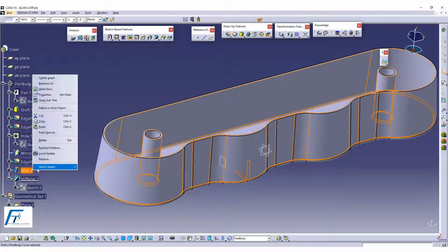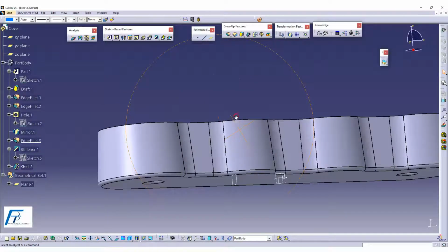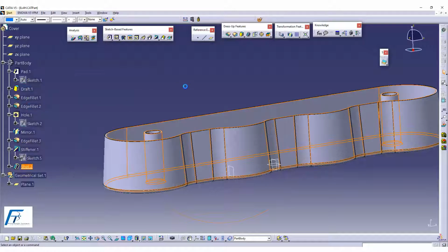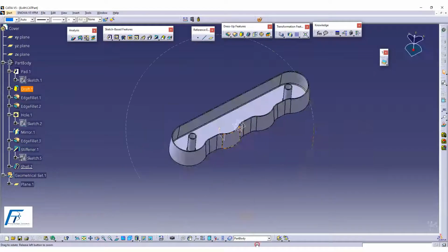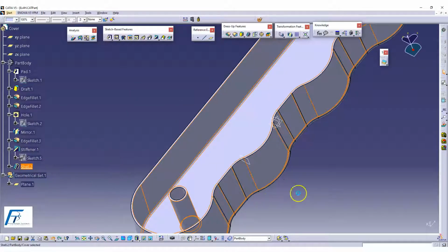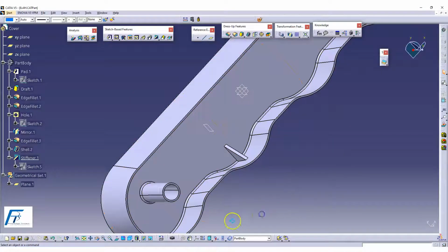If you move this shell, reorder this shell after this stiffener, you just see what is going to happen. I just moved your shell, now you give it, that could be the case. The stiffener is not going to come, so very important. That's a very important factor. Or you would like to change this hole after this shell, you won't be able to see this projection.